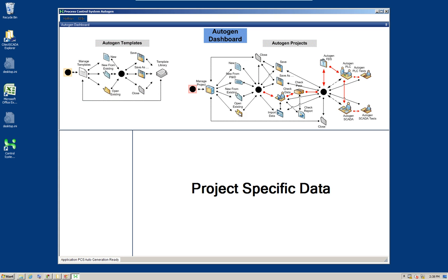For instance, for a new motor that he decides needs to be added to the existing control system, he can enter a record only for this motor and auto-generate data only for that motor, and then later on import all this auto-generated data into the PLC code and the SCADA system and add a motor in that way.